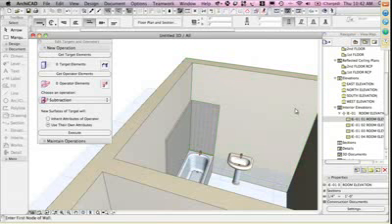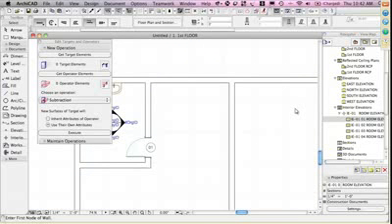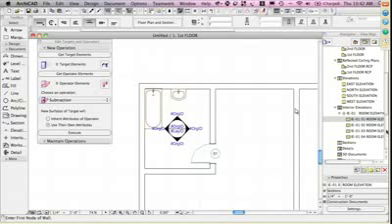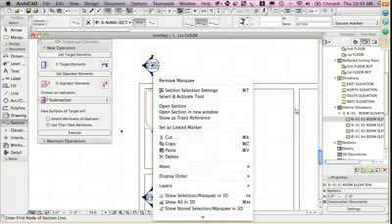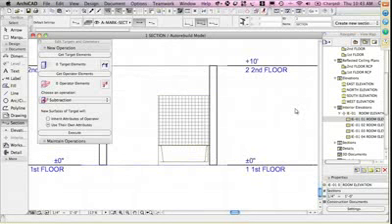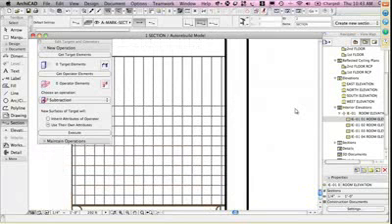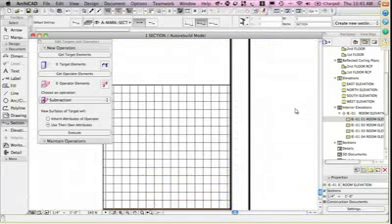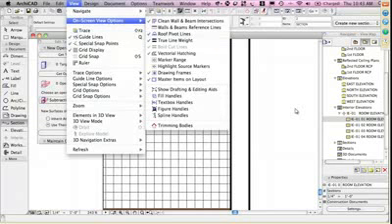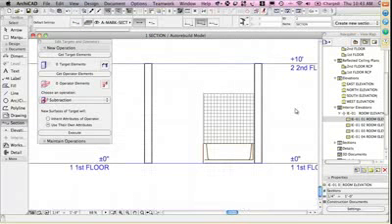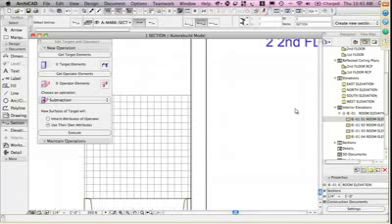And if I were to do a section through this, let me just do a little temporary section just to show you what's going on. If I do a section through this here, like a wall section might be typical, we're actually not seeing it, because it's 1 inch thick. I guess let me turn off true line weight, and oops, why are we not seeing this? Oh, I guess because these two walls are exactly the same material. So in fact, there is a wall there.